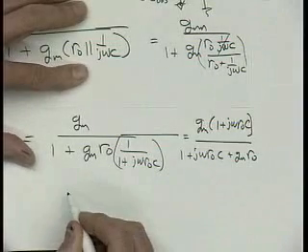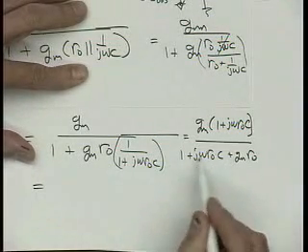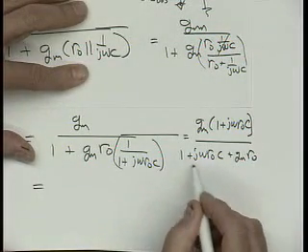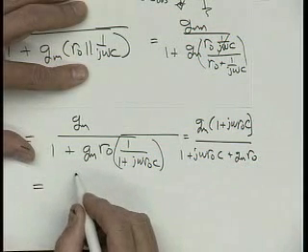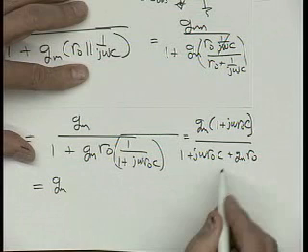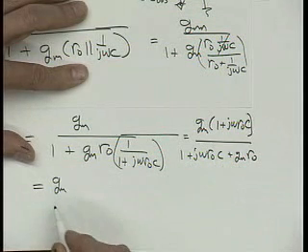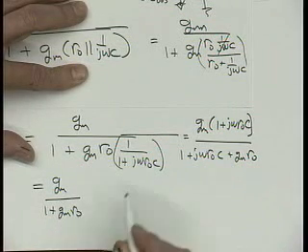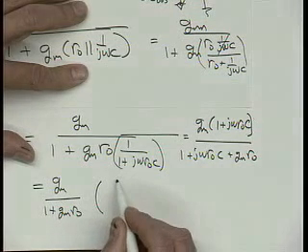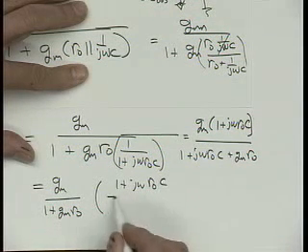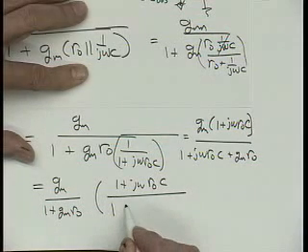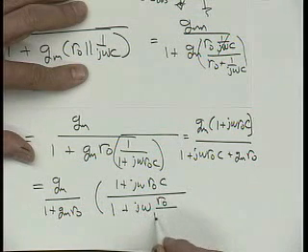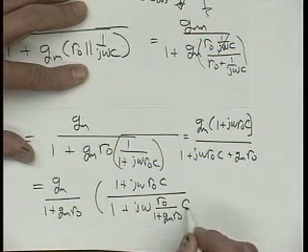Right units there. Okay, now I need to get this into the form that we always like, a 1 plus something or other. So how do I do that? Well, I need to divide by 1 plus GMR0, so let me do that. I have GM here, and I factor out a 1 plus GMR0, and I'll end up with 1 plus j omega R0c over 1 plus j omega R0 over 1 plus GM R0 times c.